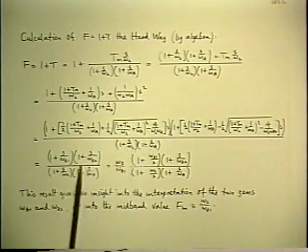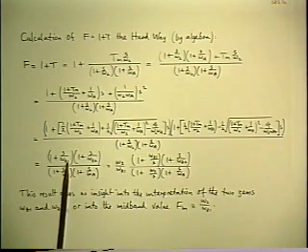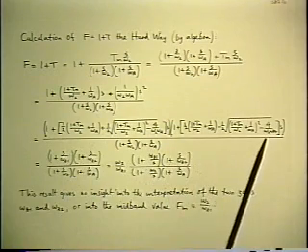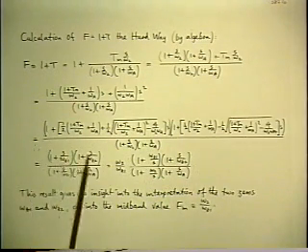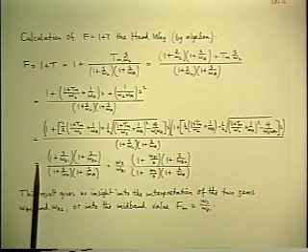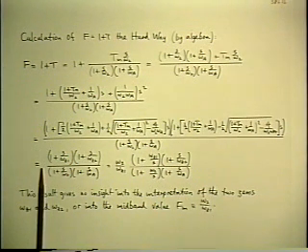And even if you just define it as an omega z1, as I've done here, notice that what comes out of the algebra has unity coefficient in front with normal zeros and normal poles, so you've effectively chosen the zero frequency asymptote as reference, which is 0 dB.